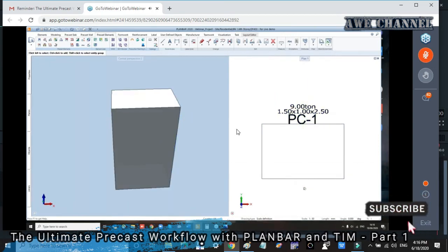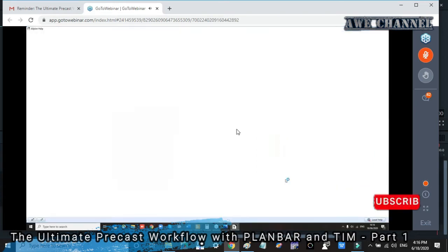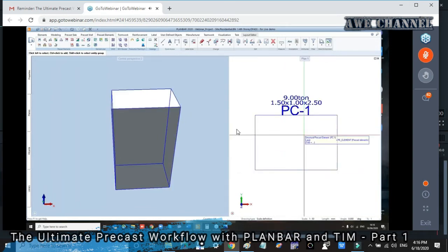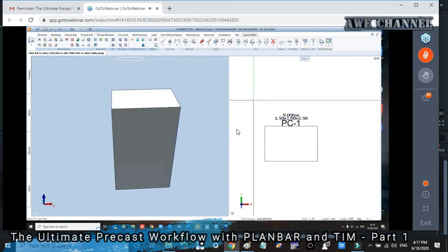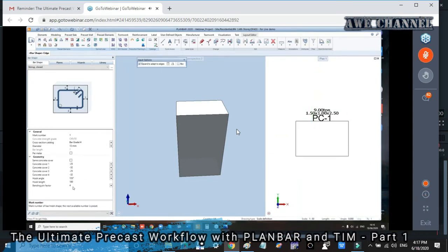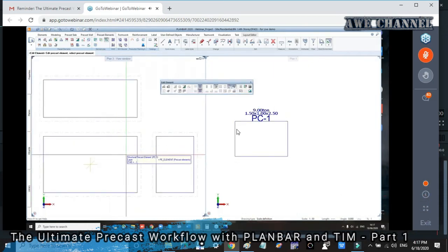So how are you going to make this 3D model the same as per the standard? Let's say, for example, I'm going to put in reinforcement. Since this one is a precast, I can already put in reinforcement. Basically, I will first use the links. And by the way, I can go to create views or edit element, same as my colleague has done.